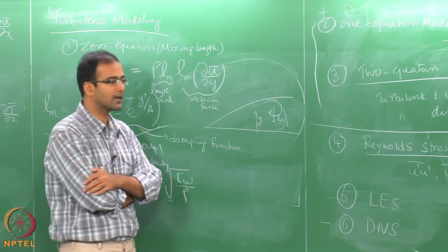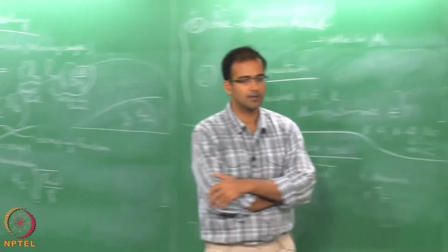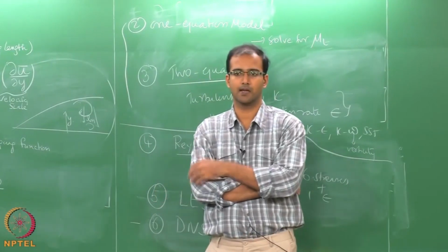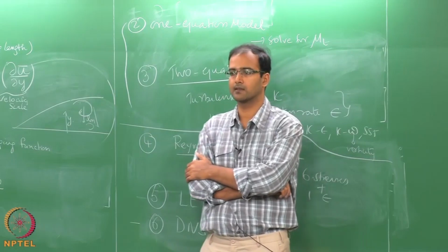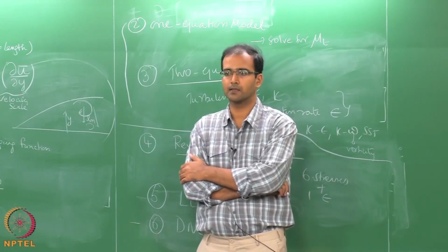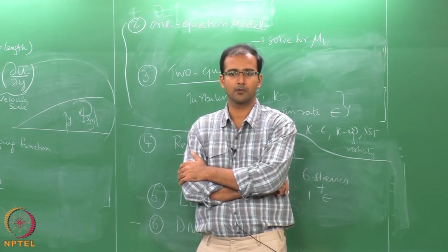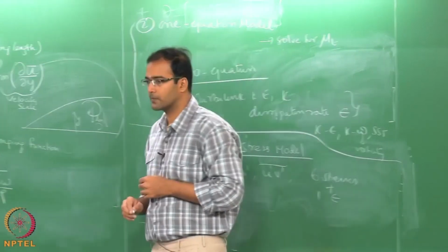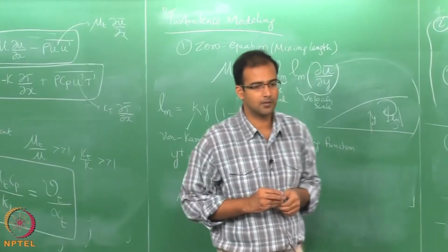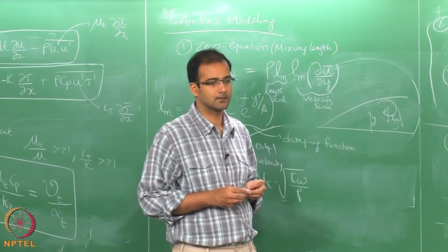As long as you can construct an engineering approach to solving turbulence, I think that is a more sustained practical approach. Although we have techniques using LES and DNS, I do not think these are well absorbed in industry yet. They are mostly academic exercises. Most practical engineering problems have been designed with at most the 2 equation models.